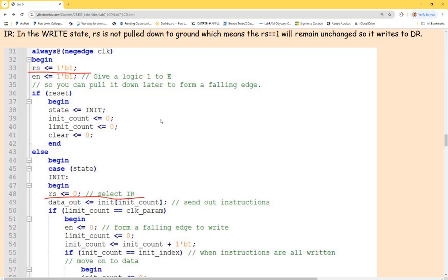Well, like I told you guys, Verilog is a hardware description language. It's not like C++ or Python, where the instruction pointer takes instructions one by one and executes them in the CPU, as a loop coming back and forth. This is like an implementation. After everything is implemented, it's like hardware, ready like a chip on the FPGA. And the clock signal for the always block over here is updating all the states of the registers.